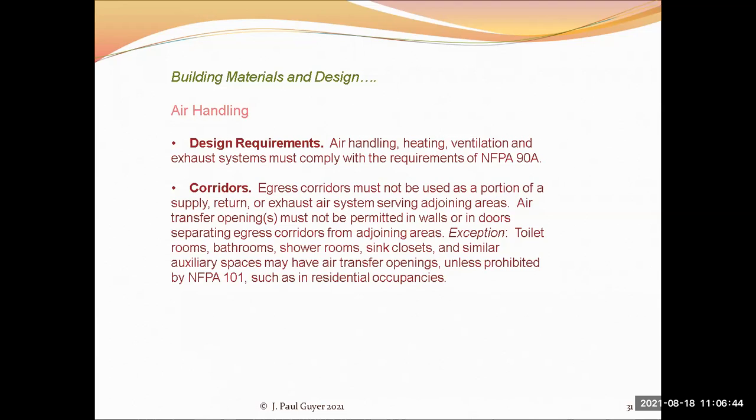if a fire breaks out, typically you would want to immediately shut off the fan that is moving the air around the building through the ductwork system, so that the fan is not assisting to move the smoke from one area to another.